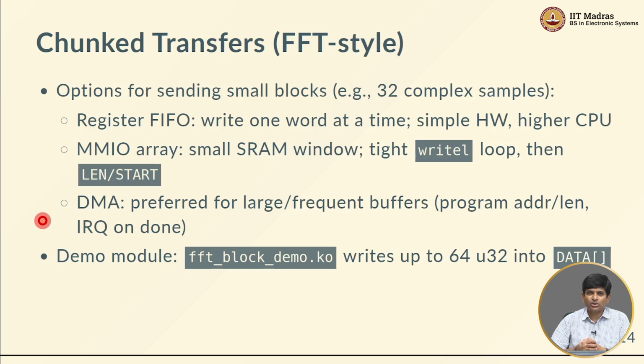So the question becomes, in the drivers that we have looked at so far, I have a way, for example, of setting the period of the smart timer or the duty cycle of the smart timer. If I have one 32-bit value that I want to write, that's easy enough to do. But let's say that I have a block of data that I need to transfer into my system. Now how do I even do this? Should I have separate addresses corresponding to each and every individual location present in memory? That is of course one possibility.